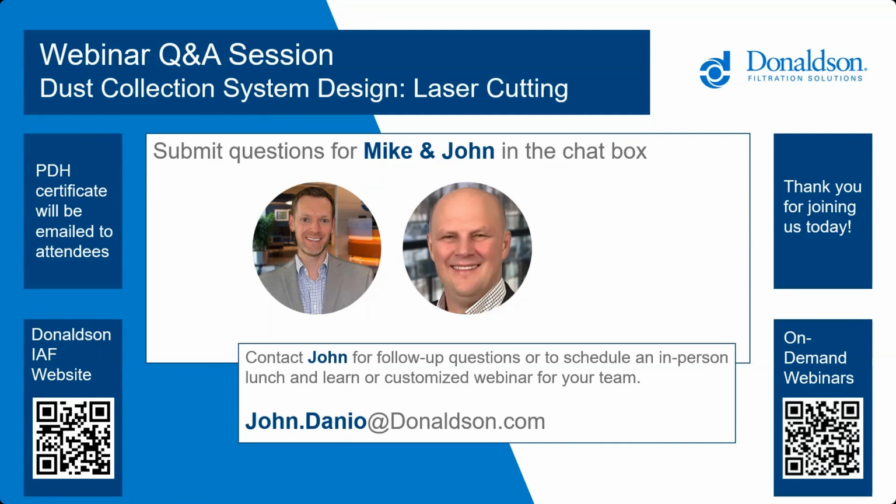Typically, I think the biggest challenge we're seeing nowadays is as the laser powers continue to grow and they cut faster, they cut more material. You run into folks trying to use the same dust collector maybe they used 5 years ago. That may not be an applicable solution for today's lasers. So something you're definitely going to want to look at. I would say undersizing the dust collector itself would probably be the biggest challenge that we run into.